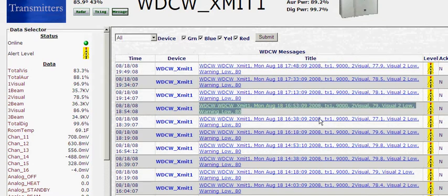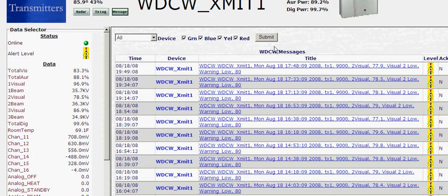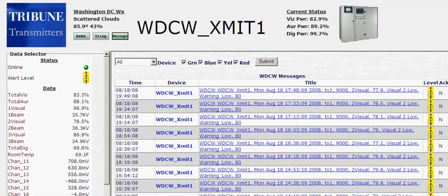This system has a root cause analysis built in, so when your transmitter is off the air, if it sees there is no mains power and the generator is not running, it will root cause back to those. If your transmitter has power and one of the drivers has failed, it won't tell you that the thing is off the air because your output stage has failed. It'll actually tell you that there's a loss of power at the driver, and it will show the things that are affected as dependent alerts below it.